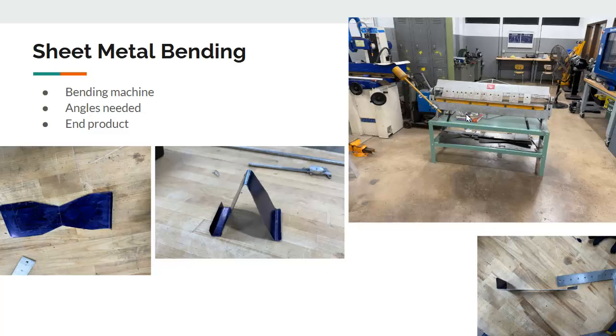As you're doing it, you watch how much you're bending it to see how far until you get to your desired angle. For us, we had to get 3 of these to 90 degrees, and the last one, which is the one that made it actually stand, or bend in half, to 120 degrees.